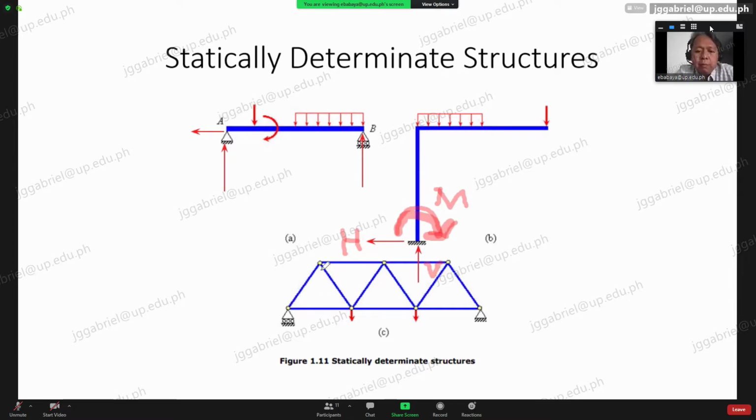All of your members in here are assumed to be axially loaded. And along with that, assumptions also would be the connections here, okay, the nodes are frictionless. No? So if they are frictionless, there won't be any moment, no? The restraint at the nodes.